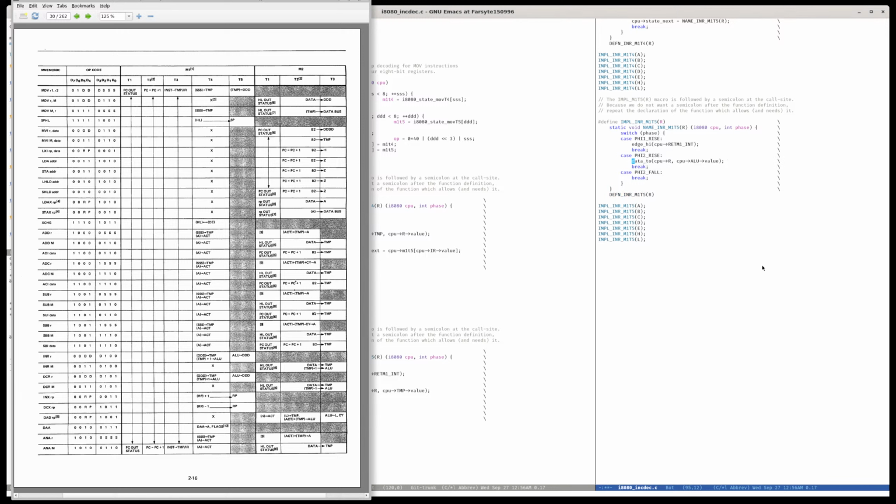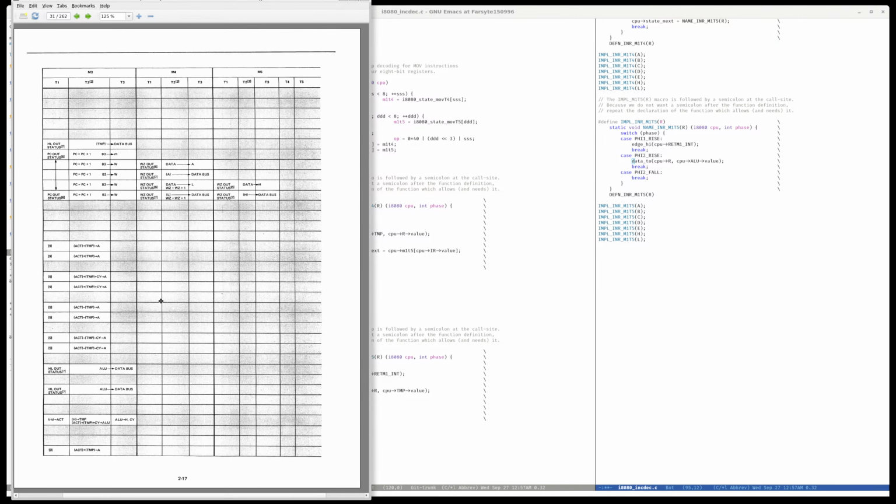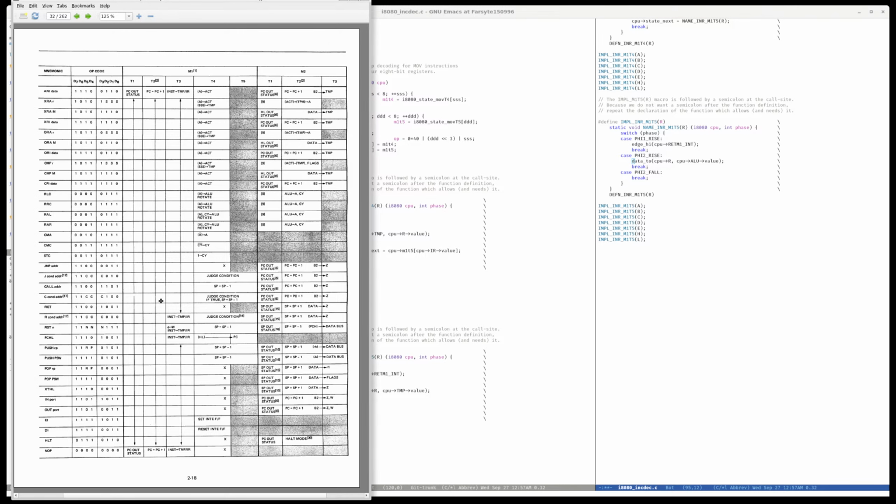Now, actually, it's quite possible that we have many different places where the ALU goes into the destination register. Let's take a look at the thingy here, and what I see is increment register, decrement register. MOV uses temp rather than ALU.